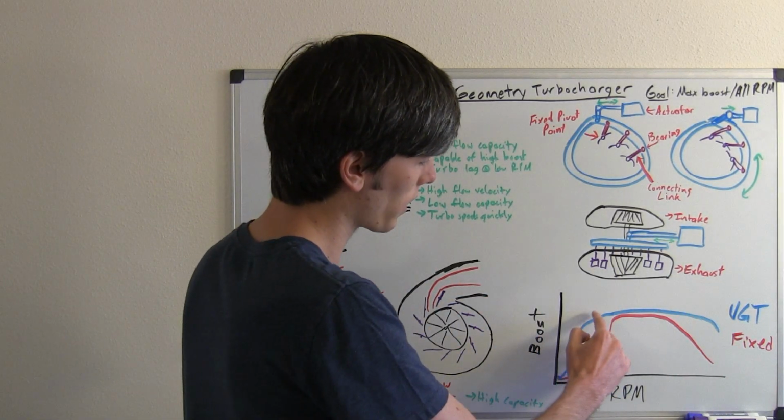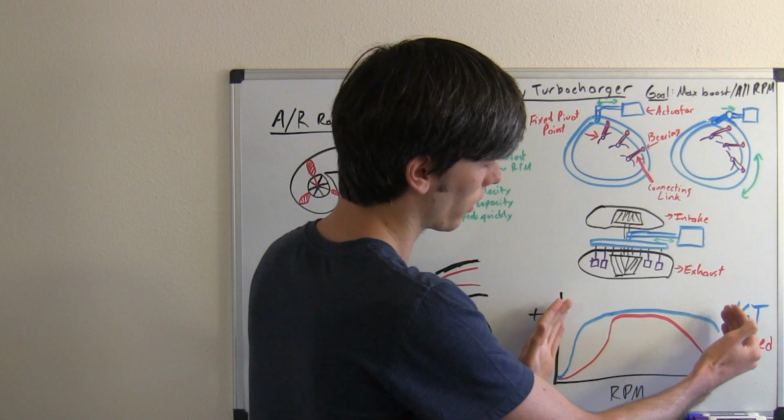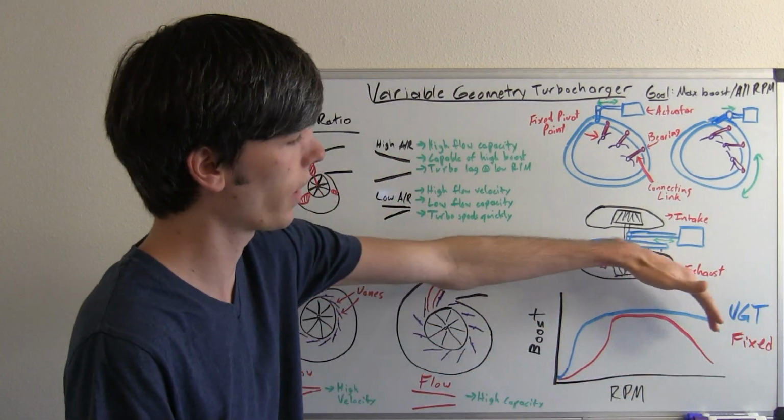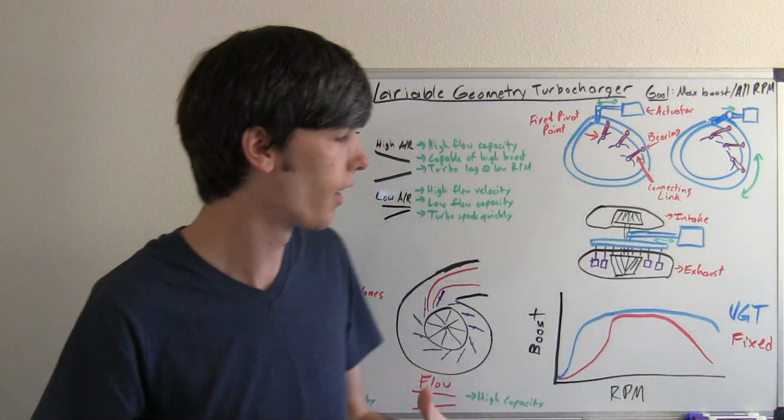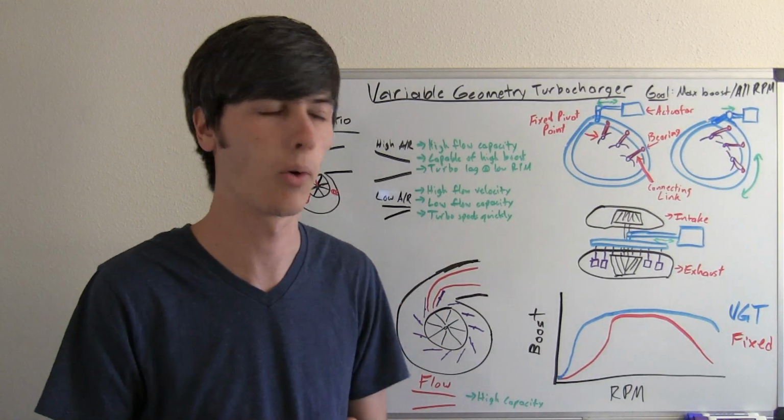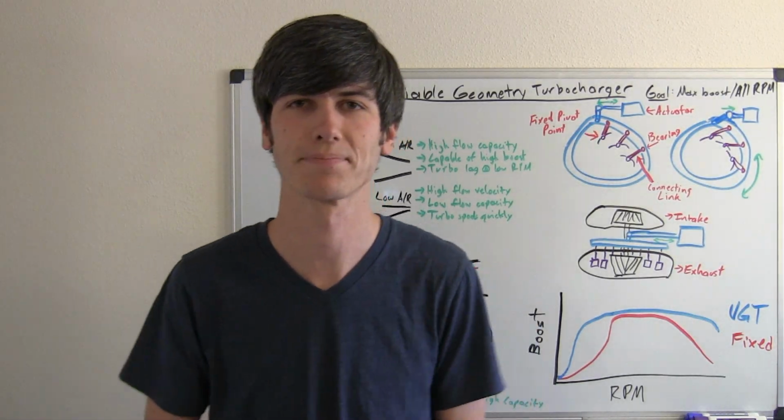So it's going to get boost quicker, and then it's going to keep that boost longer, and it's going to have a much wider rev range for which you can have maximum boost, thus having maximum torque and maximum horsepower for that rev range.